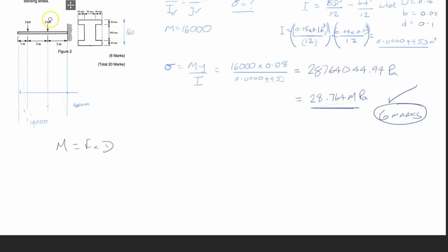However, they sort of compound. So you've got to work from the pivot when a cantilever and go along. So I'll do it again. So at point 0, the force, well, there is no force, it happens. Even if that was a million kilonewtons, the moment's still 0 because it's 0 distance from the pivot. Okay, so 0. 2,000 times 2 takes us to 4,000.